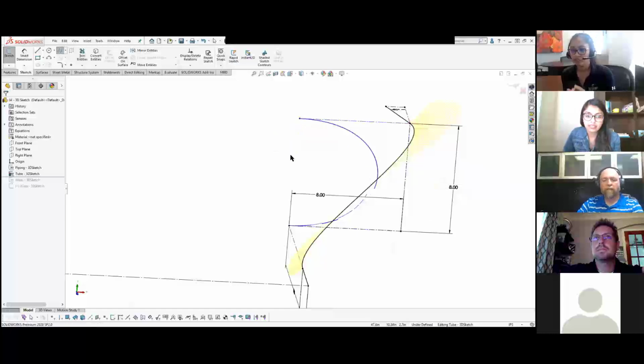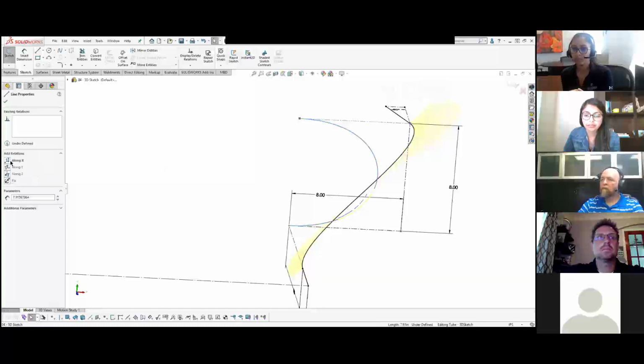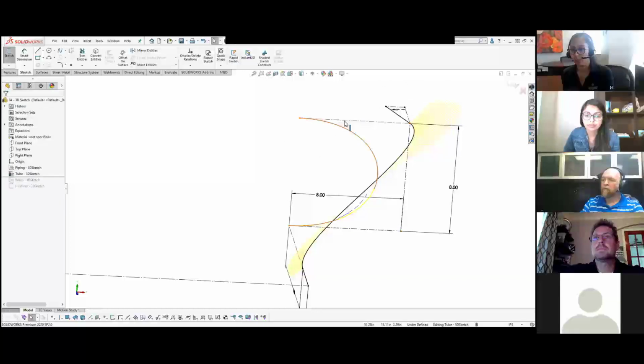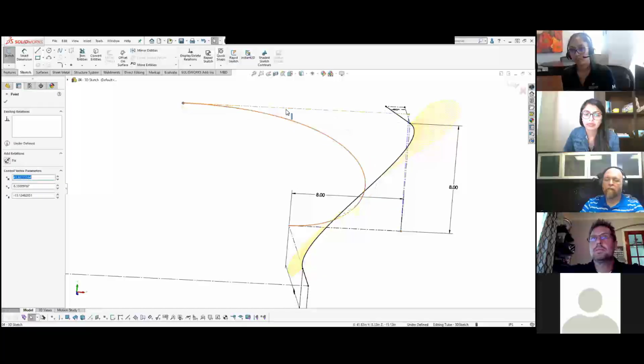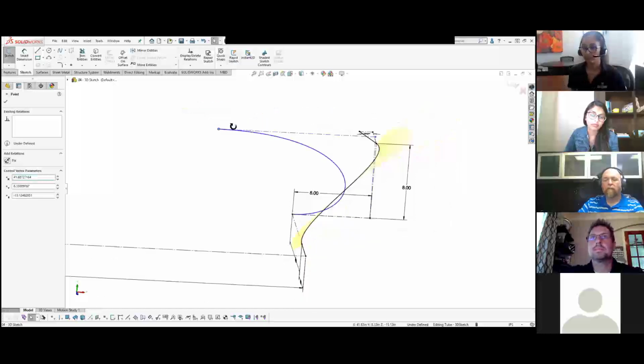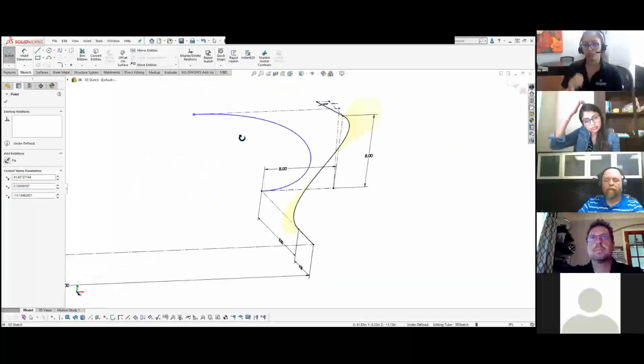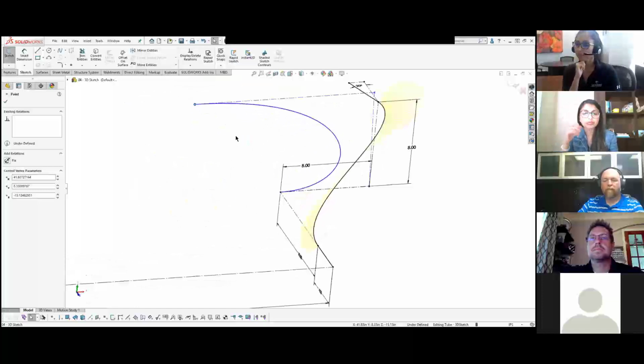So for Gregory, Darcy's doing this style spline method, which automatically puts construction lines around your spline. It makes it so much easier to fully define it because it's something we're more used to, right? Horizontal, vertical relationships, dimensions. I think it works a bit easier.